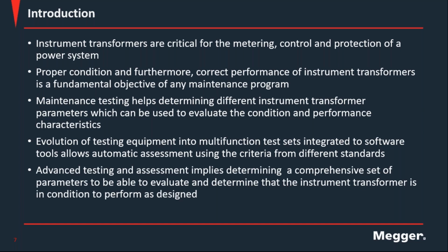So the advanced testing and the assessment implies determining a comprehensive set of parameters from the testing of the instrument transformer, and then evaluating and assessing if that instrument transformer is performing as designed.